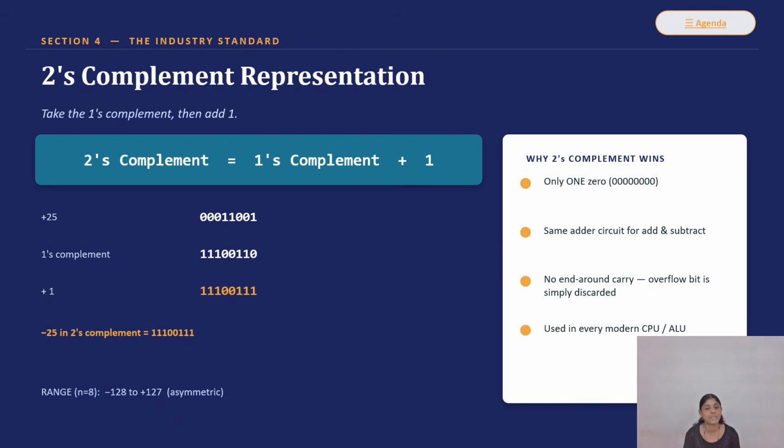Right? Okay. What is the one difference there? You add 1 with the least significant bit. So you are adding 1 with the least significant bit. So that's why here the range is getting changed. In the earlier two cases, what are your ranges? Minus 127 to plus 127. But here what is the range? 1 is getting added, which means 1 bit is getting added. That's why it is minus 128 to plus 127. Right? Okay. So here we call it an asymmetric representation.